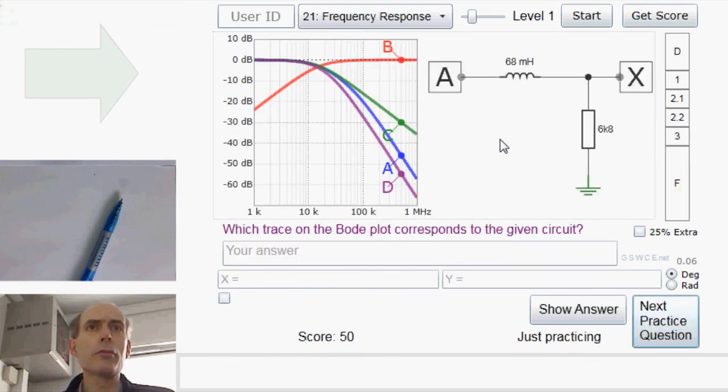And another one of these, another LR low-pass filter. So it cannot be B, but it could be C, A, or D. Here we can instantly tell that it must be C, because C is dropping from minus 16 to minus around 36, about 20 dBs in 1 decade of frequency, from 100 kilohertz to 1 megahertz, whereas both A and D are dropping faster than that.